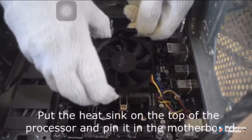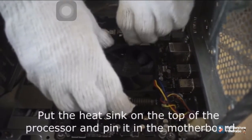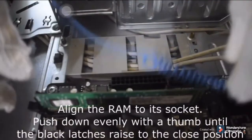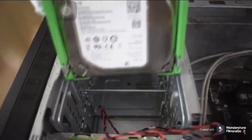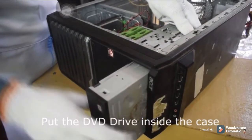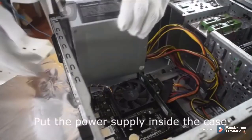Next, put the heatsink on top of the processor and pin it in the motherboard. Then, align the RAM to its socket. Push down evenly with the thumb until the black latches raise to the closed position. Then, put the hard disk drive inside the case. Put the DVD drive inside the case. Put the power supply inside the case.